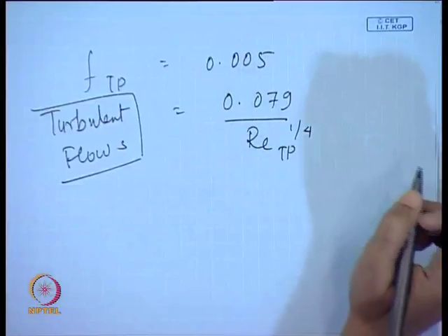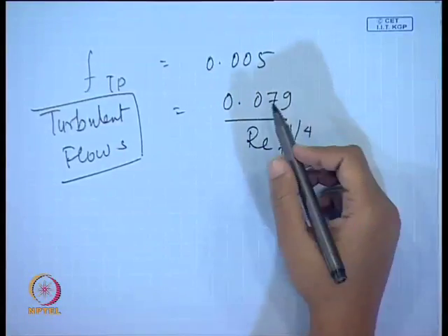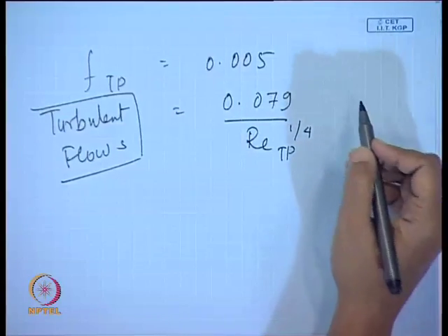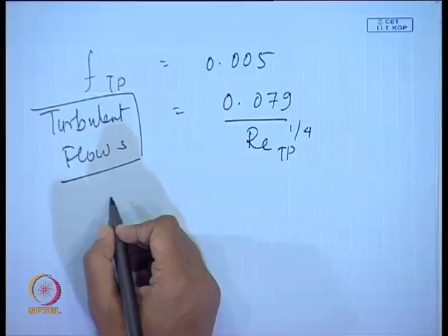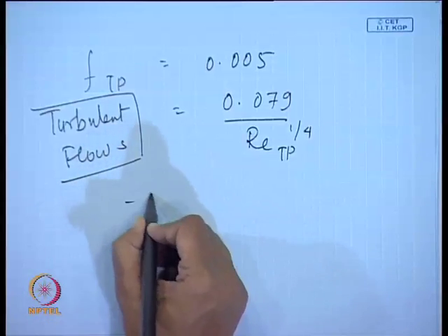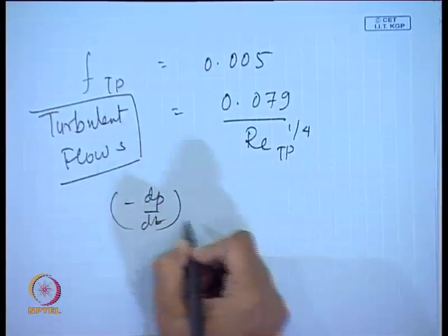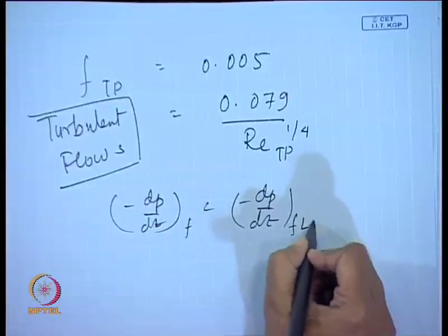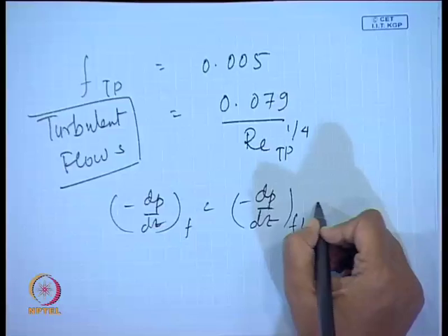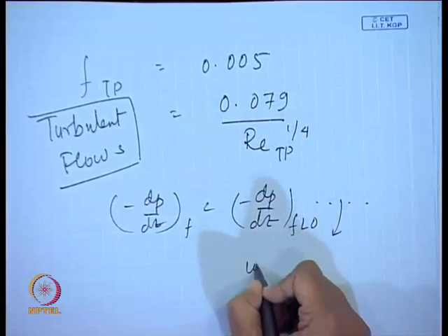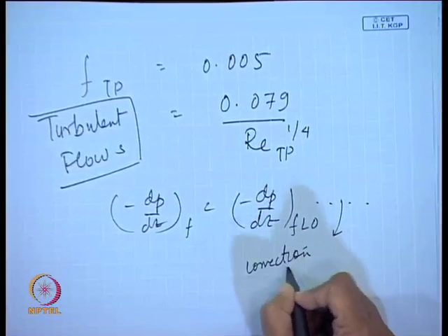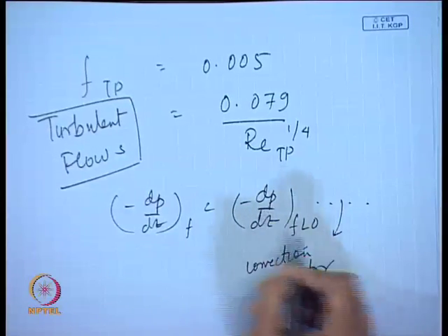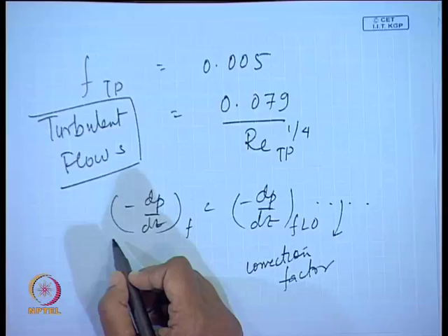Any of them we can take and accordingly we can substitute it, and if we proceed, then you will find that in a similar way you will be in a position to express the frictional pressure gradient as the frictional pressure gradient for liquid flow only and some sort of a correction term or a modification term which needs to be added to the single phase pressure gradient in order to obtain the two phase pressure gradient.